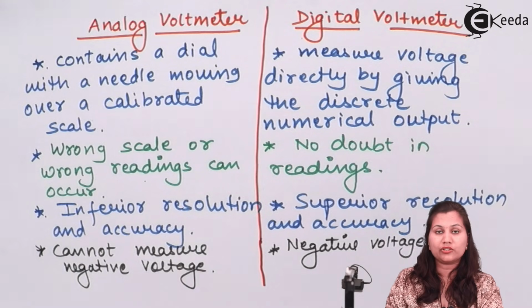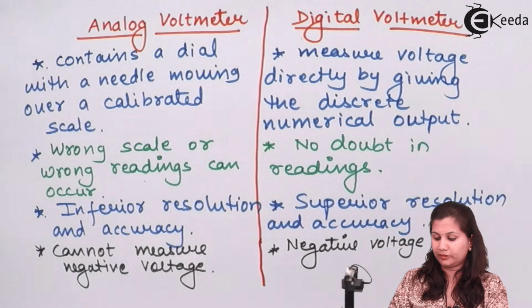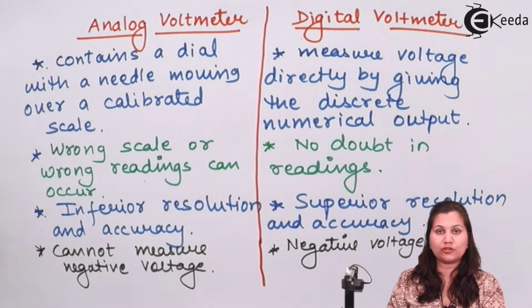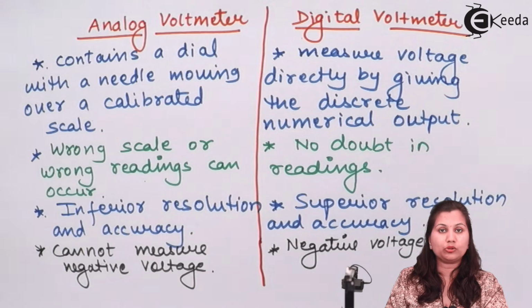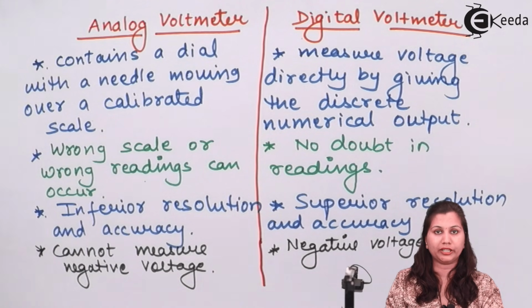Another difference between digital and analog voltmeters is that in a digital voltmeter, no damage is going to occur if this instrument falls from the table. But in analog voltmeters, if the device falls from the table, it is going to be damaged because the scale will be disturbed, and also the scale has a glass over it, so that glass will be broken.